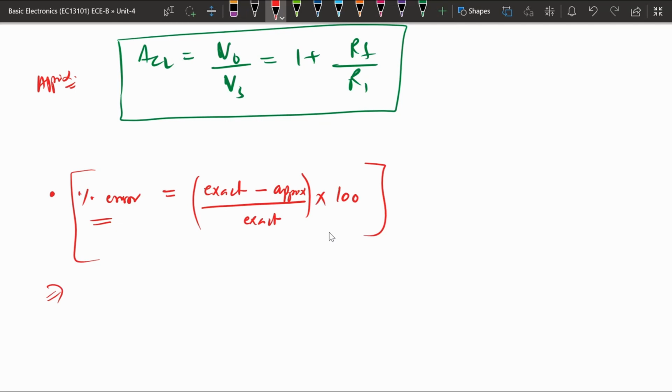If both the inputs are applied with some voltage, that configuration of operational amplifier is called a differential amplifier. We have the input at both the terminals, that will be differential. In that case, we get the analysis by utilizing the superposition theorem and applying the inverting and non-inverting concepts. We can get the value of gain, and from there we can get the value of output. So this is all about the operational amplifiers connected in inverting and non-inverting configurations.